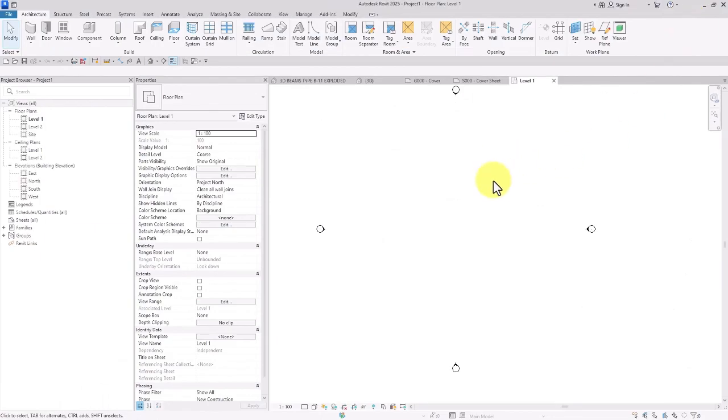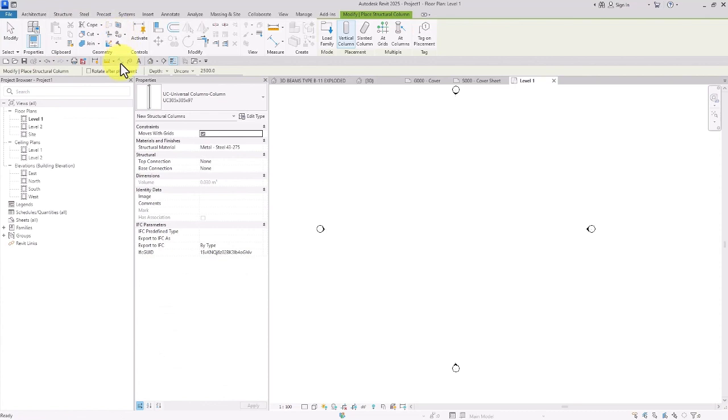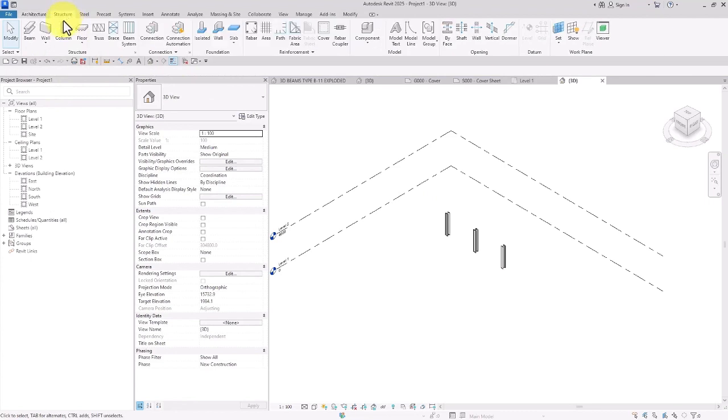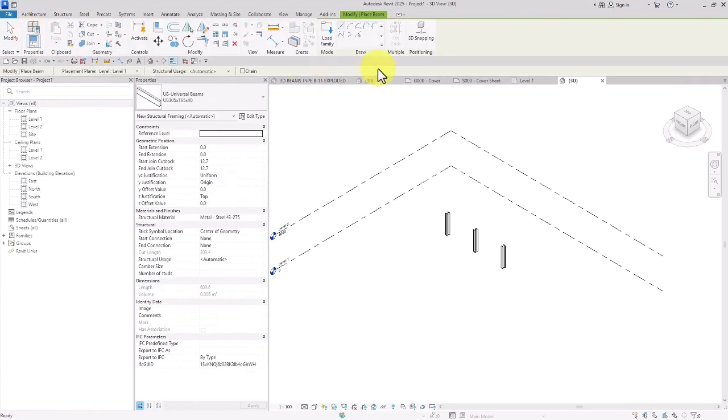Alright, anyway, the first item that we wanted to discuss is 3D snapping. Basically, when we are working in Revit, for some of the tools, we have some 3D snaps. To give you an example, if I go ahead and create something like a column in my viewport, something like this, and then if I select BIM, for example, we would see that instead of having 3D snappings in our option bar, we have them in the Ribbon.